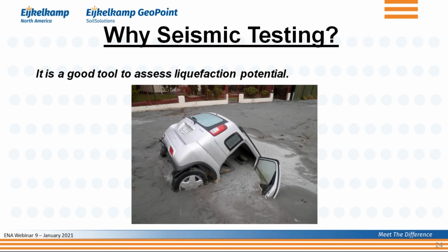Now, because liquefaction causes all kinds of damage, and the way to find liquefaction is with seismic CPT or downhole seismic testing, this is why you want to perform seismic CPT to get a better handle on that liquefaction potential.